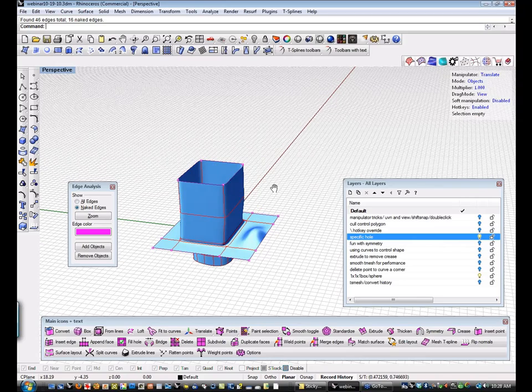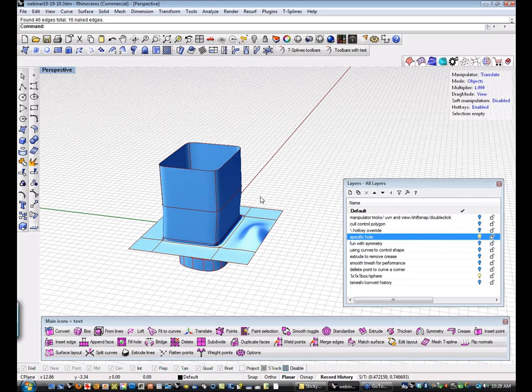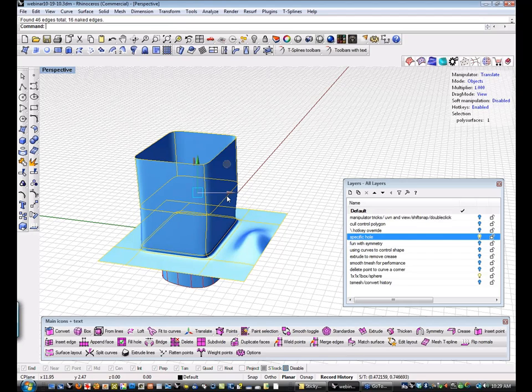So it doesn't always have to be a T Splines bridge, doesn't always have to be a T Splines transition. You can work within a model and use T Splines for what it's great at, use Nurbs for what it's great at, blend the two together. They can coexist in the same model, and then you can have these very mechanical, very controllable aspects of your model that can blend in with really nice organic pieces, and everybody gets along just fine.